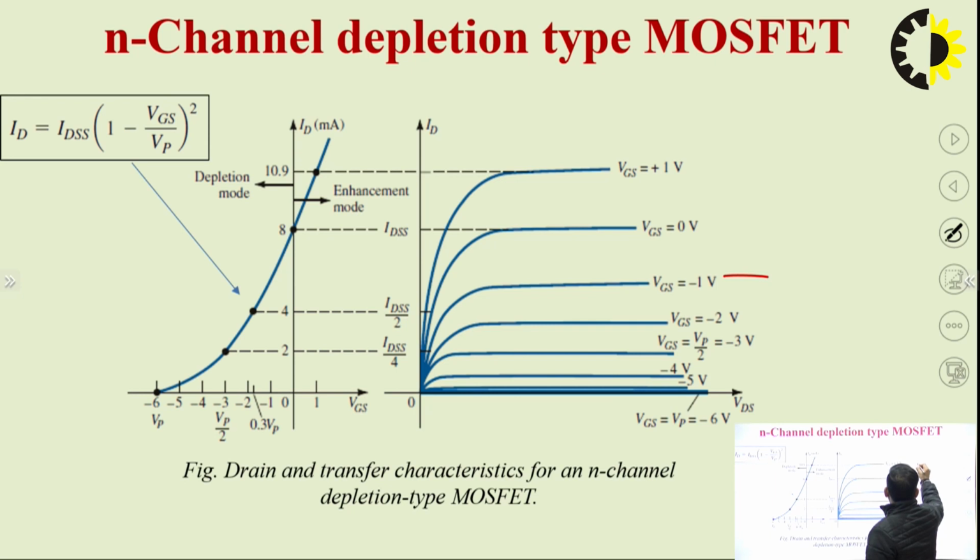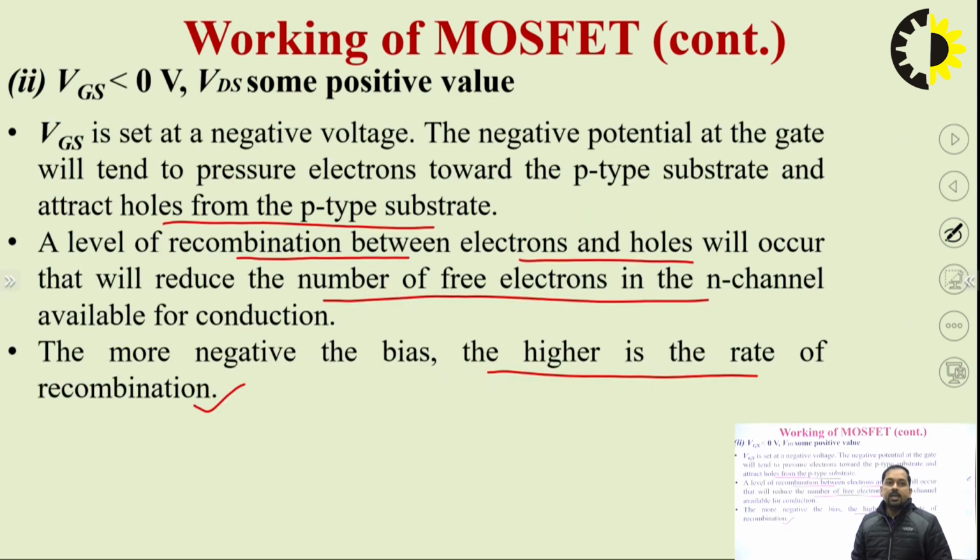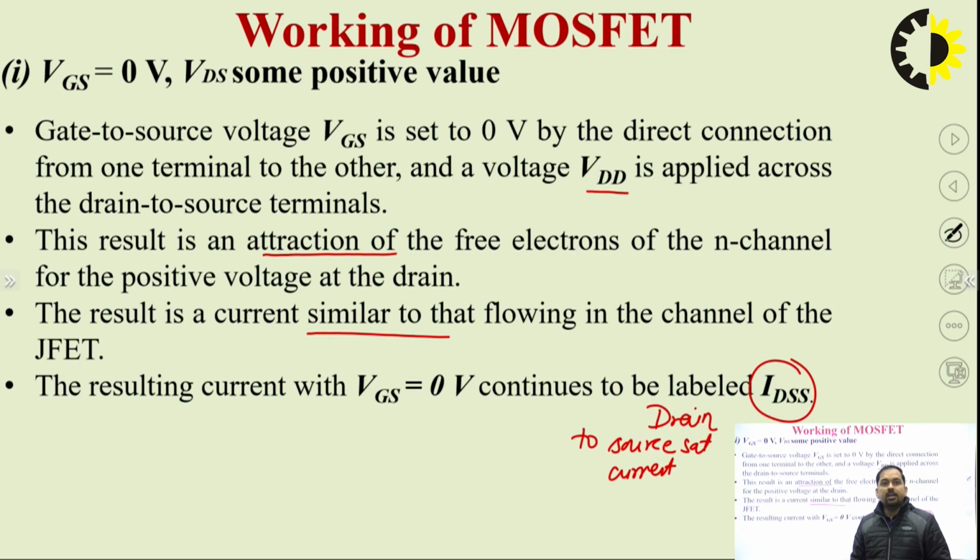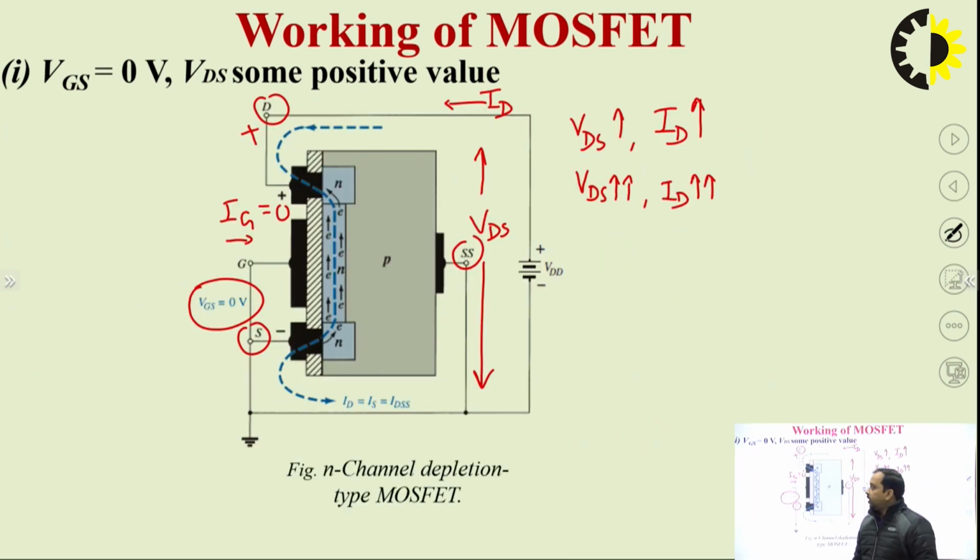We can observe clearly in the characteristics what D mode is and what E mode is. So first of all, we'll be seeing the characteristics. Now what are the characteristics? We can clearly see from this particular circuit that we have output characteristics, which is between ID and VDS for different values of VGS, which is termed drain characteristics or output characteristics.